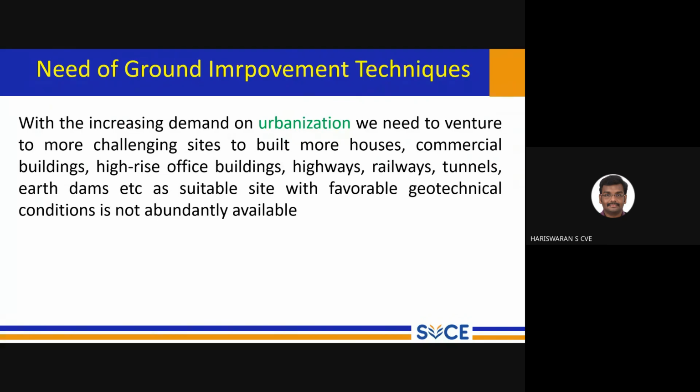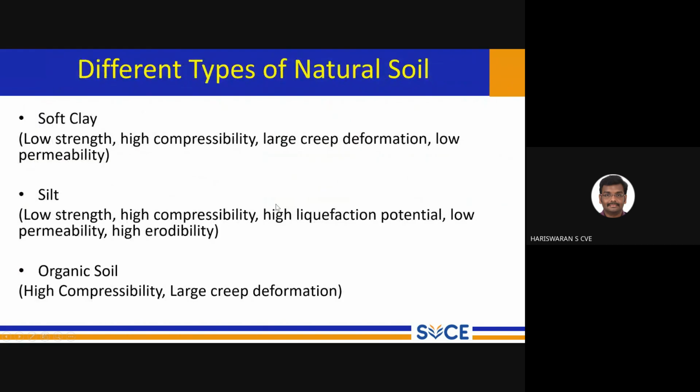So before executing that, n number of soil investigations are supposed to be carried out. Then only, with the help of a TBM, tunnel boring machine, do we execute everything. But geotechnical characterization and enhancement of the soil along the path prior to the execution of the tunnel is mandatory. So this is how the need for ground improvement techniques plays a major role.